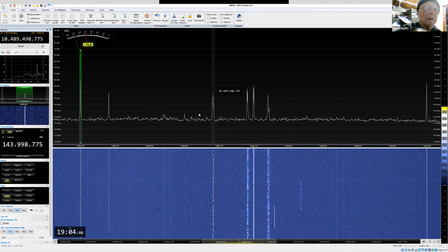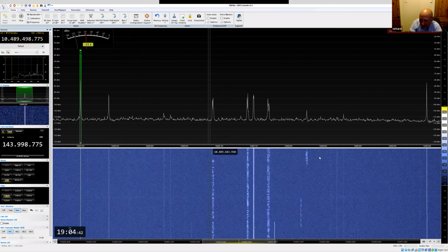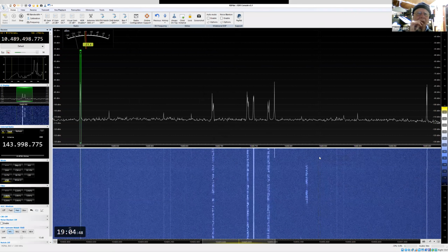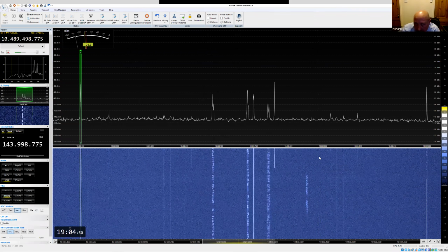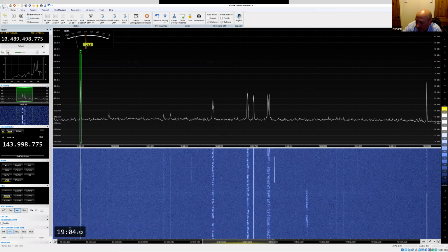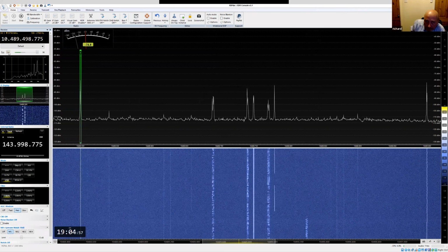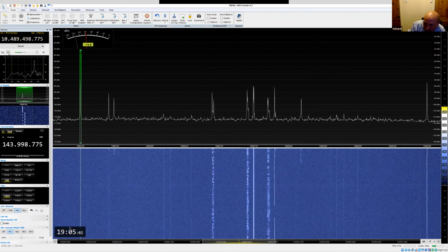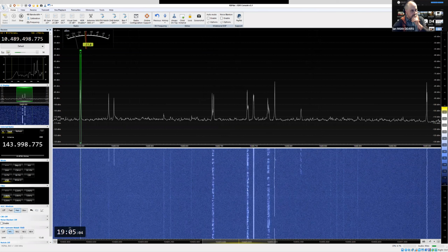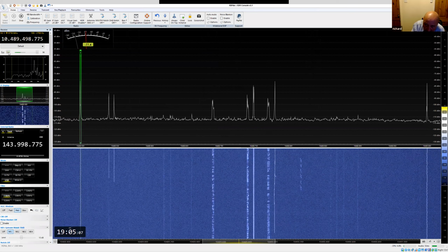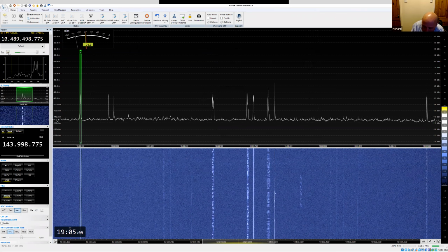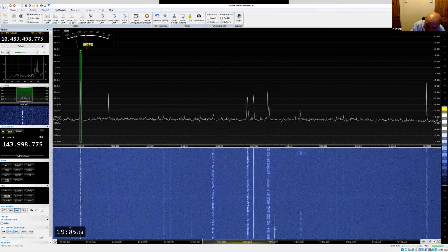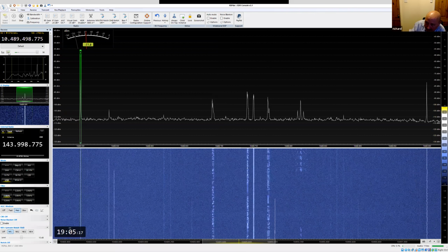Yes, yes. Okay, so this is SDR Console. Okay, so that's the beacon. So as I say, if you can work out the offset, typically it'll be 739.5 megahertz using a standard off-the-shelf LNB. You can use this to align your dish, basically.